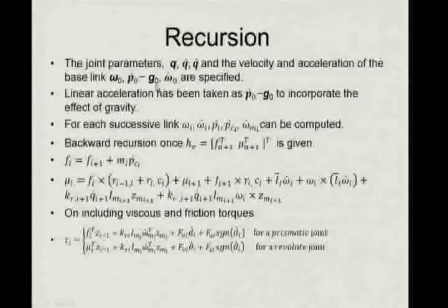Okay. So what we say is, this is something which I mentioned in the previous class also, that instead of writing gravity, gravity, gravity on each link, we just accelerate the base upward by amount equal to gravity. So that will create exactly the same effect, whether you are standing static and gravity is pulling you down, or you are accelerating upward in the absence of a gravity field, it creates the same effect.